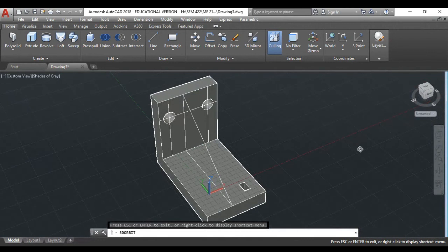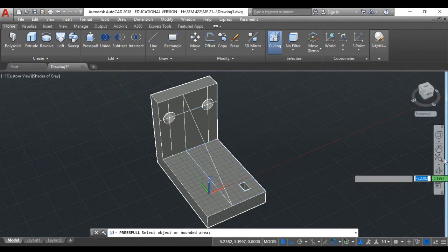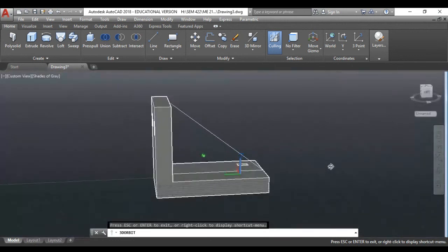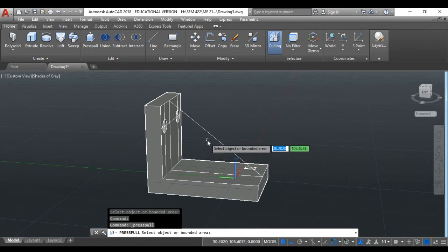Now the very last step before I claim that I finalize everything is to go and make press pull. But be careful, guys. When you make the press pull, you will face a problem here. Because when I make the press pull for the first time, it's as if I was selecting other areas. Okay, now I'm gonna make press pull for that shape. You see, guys, it does not work. Why does it not work? I'm not able to see this one change to the blue color.